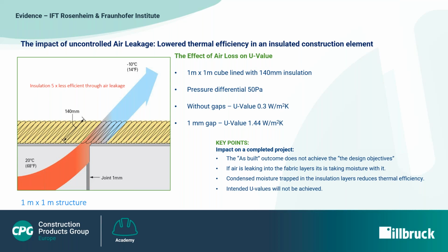Now, warm air carries moisture vapour through the layers, and when the dew point is met, the moisture condenses, leading to interstitial condensation, which can manifest itself in any of the fabric layers, including the insulation layer. Whilst combined U value and condensation risk analysis is routine, there is a failure in the traditional methods of calculation known collectively as the Glaser method.